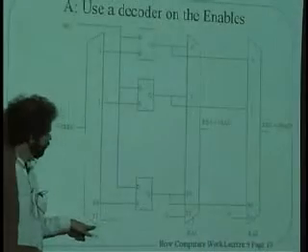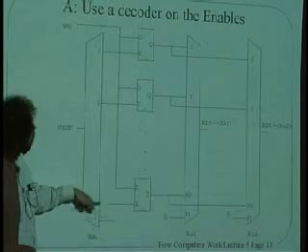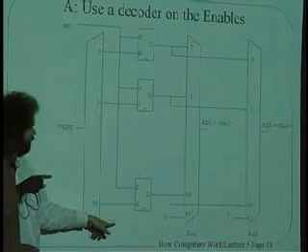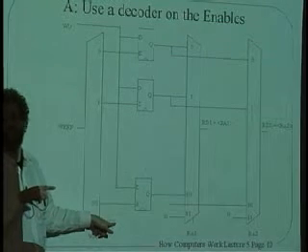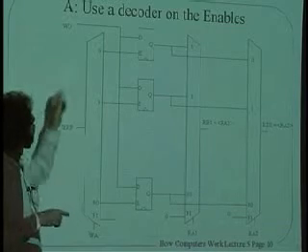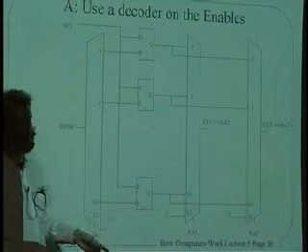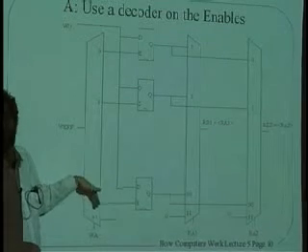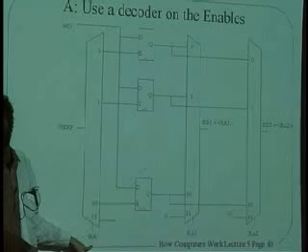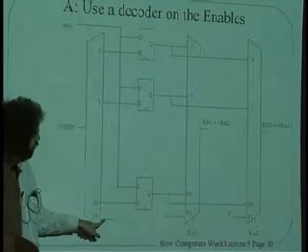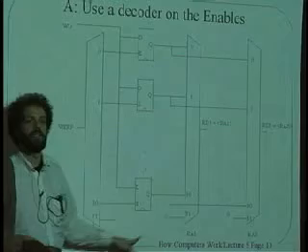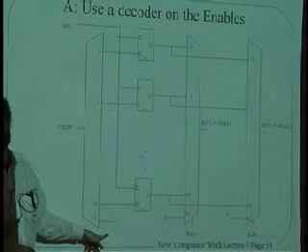Hey, look at what happened to register number 31. If we choose to write register 31, all the rest of them are going to be 0. And register 31, this little wire is going to come out here and say, poor, pitiful me, no one's listening to me. And why is that? Because the bits that come in here on WD just go nowhere. And so none of the registers is going to be turned on if we choose register 31 as the write address destination for where we're trying to write. And that's how we implement, in this very trivial way, making register 31 equal to 0 on read and ignored on write. That's all there is to it.